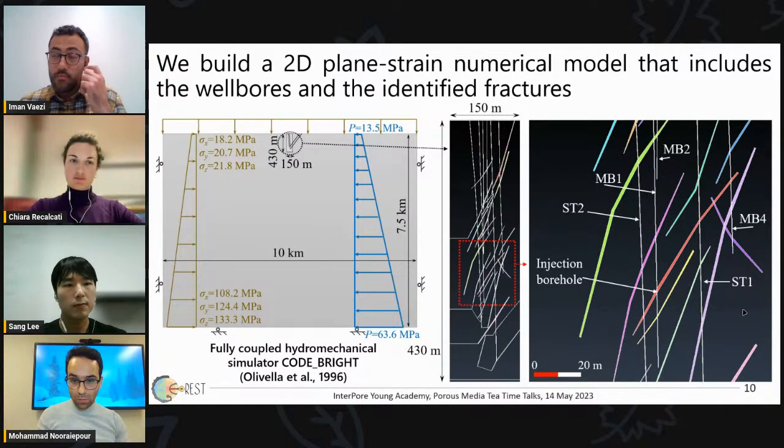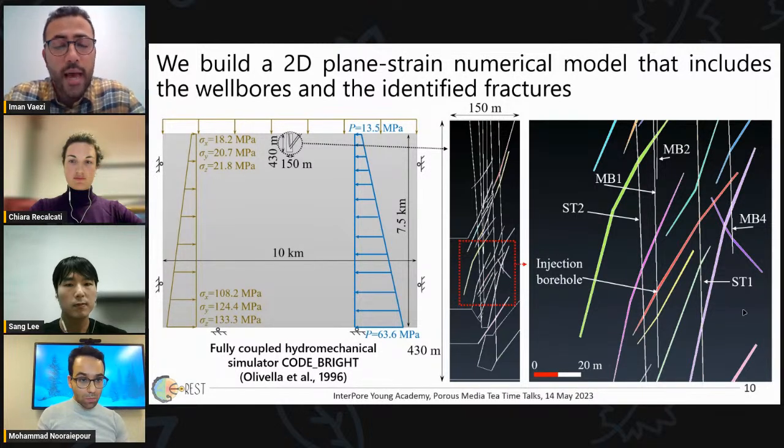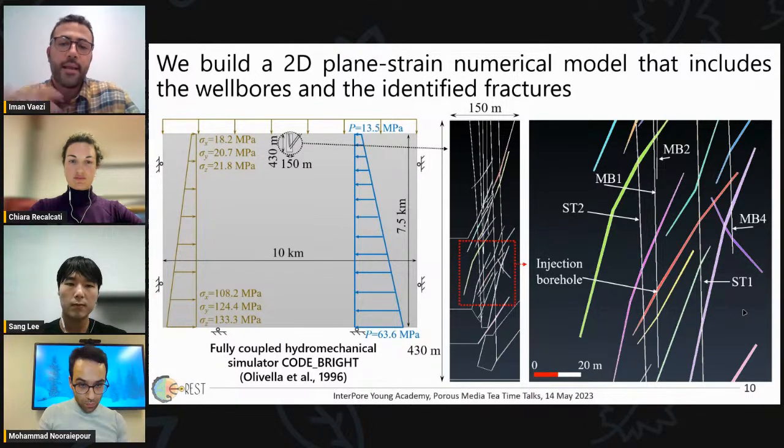We had monitored the geological loggings, so we knew where the fractured zones are and what the permeability is. These are the inputs that the Pedreto lab gave us. Based on the input, we upscale the properties to fit our equivalent continuum layers. And then we had some calibration simulations to see if we can reproduce the fracture.